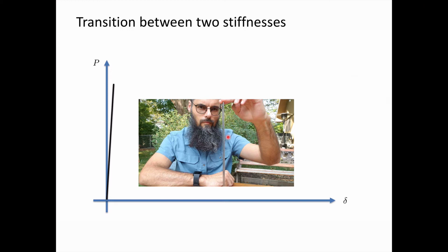Where E is the Young's modulus, A is the cross-sectional area, and L is the length of the tension or compression member. And so the stiffness is going to be really high. We have this really high spring constant that's describing the behavior in this first zone in the load deflection curve. So here's a video just showing that behavior. It's really quite stiff.